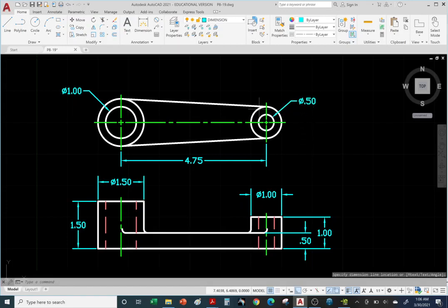If you're having trouble locating these diameter dimensions, you can simply turn off ortho. By turning off ortho, now you can use the grips. It's easier to locate your dimension by turning off ortho. You can see I have freedom to locate it wherever I want. And once again, you want the leaders pointing downward. We hit escape, and towards the center of the hole.